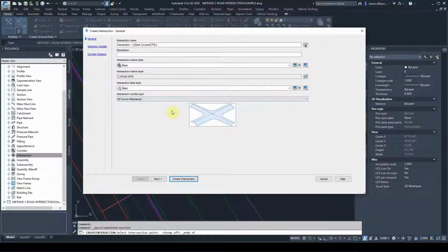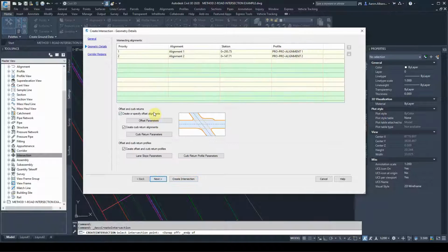That's not what we want. We want just the main road. We have a T intersection. We want the main road to maintain ground, the secondary road just to finish to where the elevations of the side of that road. Okay, so to maintain the drainage on the side of this main road. So we'll go to next.